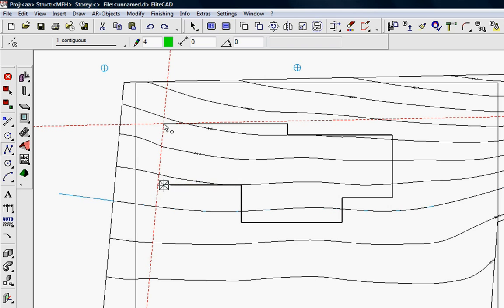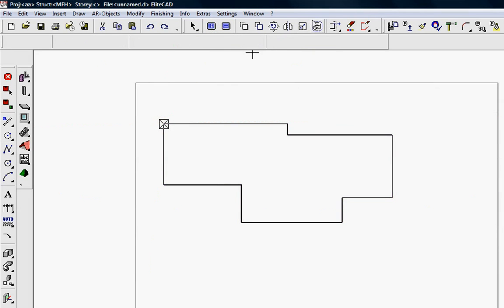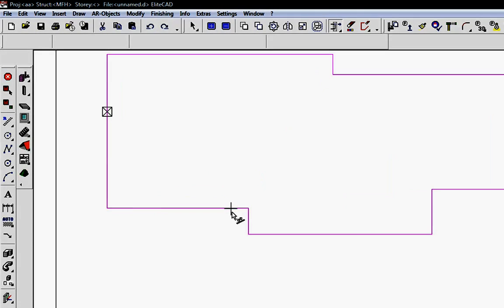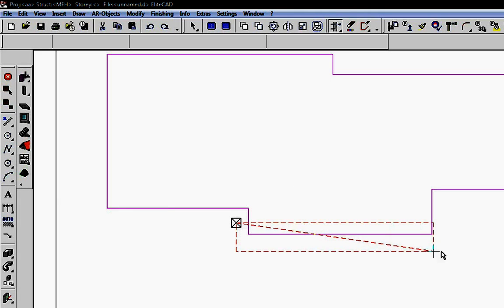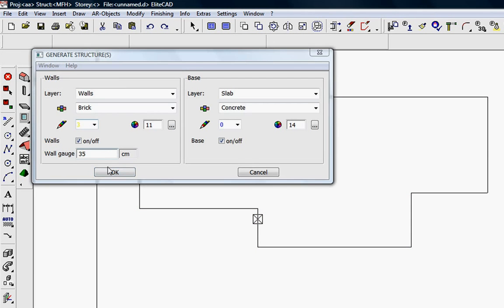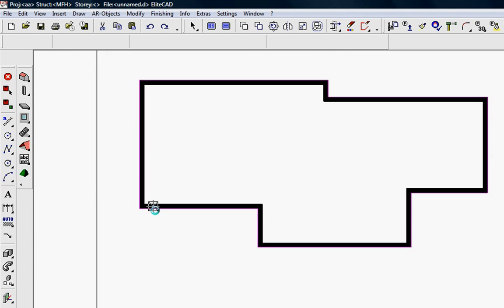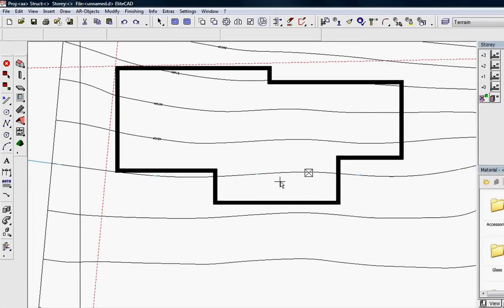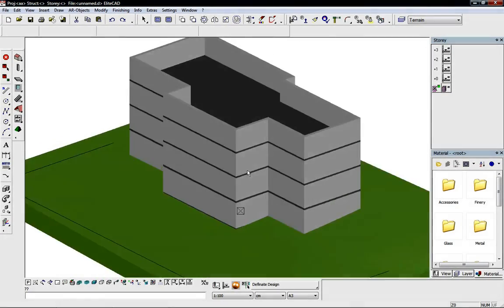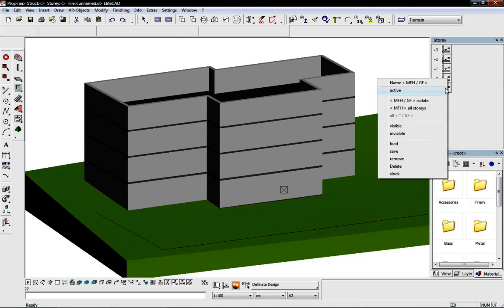We build this perimeter up as a unit, can drag it, and subsequently make adjustments to each of the dimensions. We simply click on a line and specify that we want this line to be 300 long, and then specify in which direction the whole perimeter should be extended. We define the geometry of diverse lines by clicking on them and putting in new dimensions to precisely match the building perimeter to objects of comparison. After having defined the building perimeter, we click on it and link it to the already established floor height specifications.